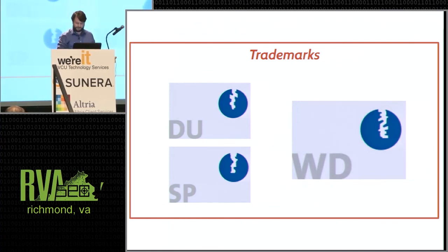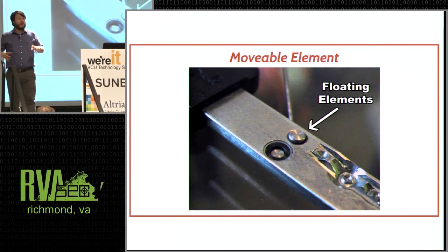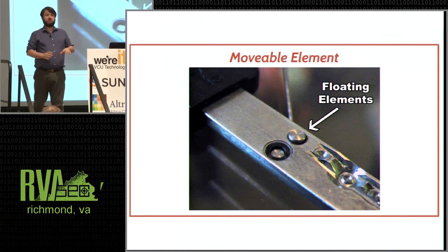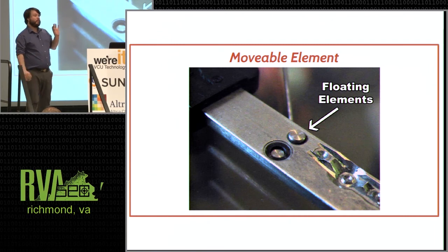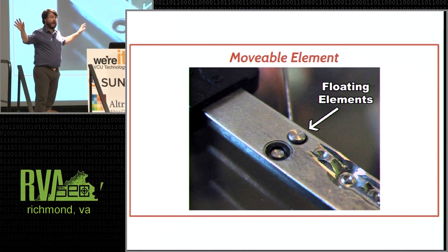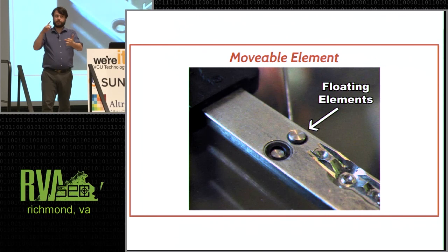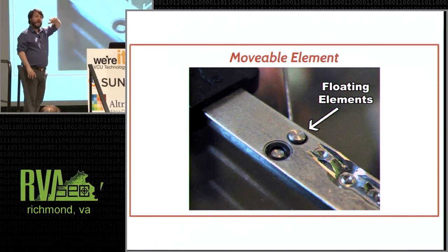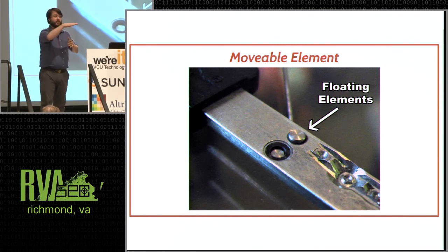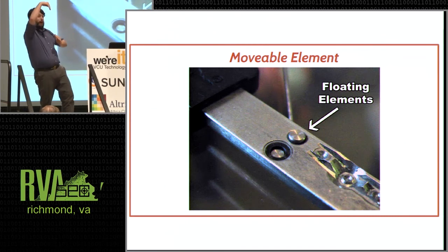But then the French Patent Office comes along and says, screw all this noise, you can't protect your keys at all unless you have a movable element in them. If you're just bringing us bare metal, we're not going to issue you a patent, you can't protect your key. So Multilock, Dom, a ton of Abloy companies, a lot of other people come out with these little floating elements. And they're actually kind of clever because as they insert into the lock, they're going to duck down under a little protrusion and then pop back up because of little dudes inside of the lock that are forcing them beyond the scope of the actual blank.